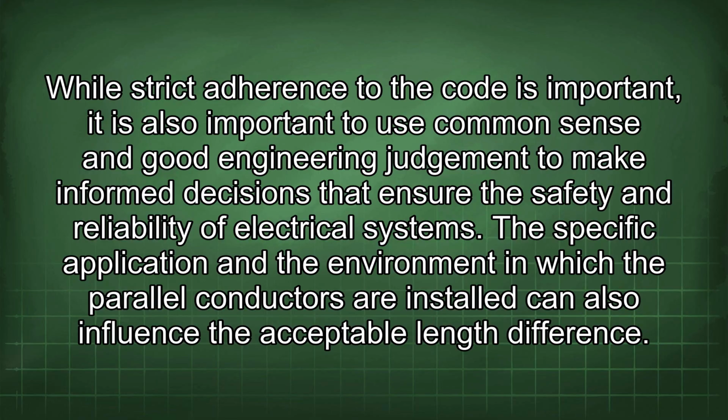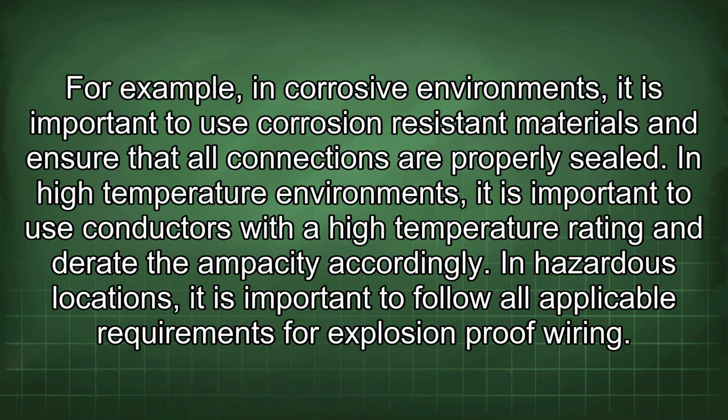The specific application and the environment in which the parallel conductors are installed can also influence the acceptable length difference. For example, in corrosive environments, it is important to use corrosion-resistant materials and ensure that all connections are properly sealed. In high-temperature environments, it is important to use conductors with a high temperature rating and derate the ampacity accordingly. In hazardous locations, it is important to follow all applicable requirements for explosion-proof wiring.